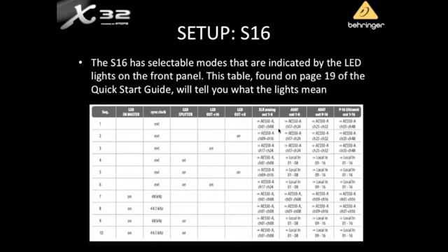When in reality, when you're using the S16s with the X32, we recommend that the X32 provides the master clock. So to do that, you're going to be working with these first 6 modes, where the sync mode is external. The other 4 modes are useful if you were using the S16s in a standalone mode, or with 8000s, or in a recording rig, as Joe mentioned.